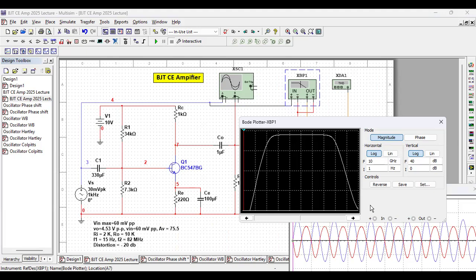So, my part of it is established that gain is frequency sensitive. Of any amplifier, gain is frequency sensitive. That mainly happens because of the capacitors used in this. And even if you do not use a capacitor, remember, any element in this universe has a reactance. It can be very small, but it has. So gain will always be frequency sensitive.